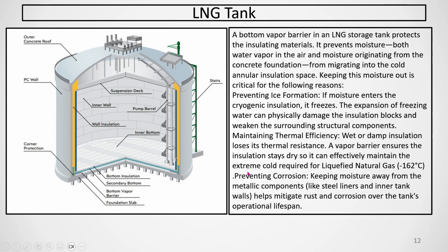That is the LNG tank. So I think, friends, I have discussed the different types of tanks, LNG tanks. Spherical tanks are preferred compared to horizontal or vertical vessels or tanks, because the surface area is less, as well as the stress developed on spherical vessels or tanks is less.